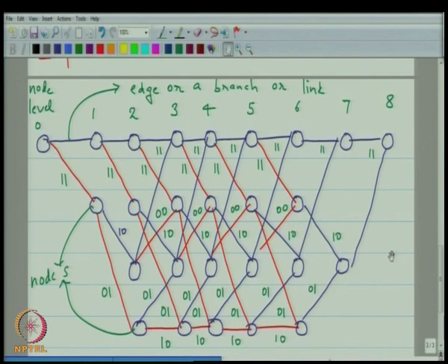But in general you get the idea that there is a one-to-one correspondence between message sequences and paths in the trellis. So, you now understand that I can associate with a path a message sequence, but at the same time I can also associate with every path a code word, because in this trellis I have also labeled the branches with the output of the convolutional encoder. So, let me just go back to this labeling that I had here. Let me just fill in.